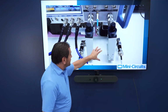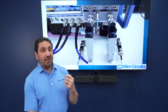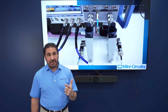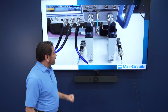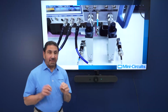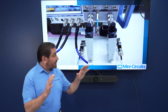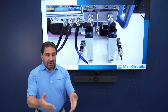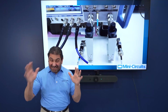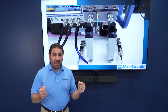So I said we're going to come back and take a look at the front panel of this. If you notice, we have signal source output. This is the carrier frequency that you've selected and the internal power that you've selected to come out of the analyzer. We have an 11 dB mechanical step attenuator, along with a fixed attenuator. Between the fixed pad and the mechanical step attenuator, we want to adjust the padding such that the input dynamic range to the amplifier takes us from compression, maybe 3 dB compressed at least, into small signal. If 11 dB is not sufficient, we change the fixed pad and do it over again.